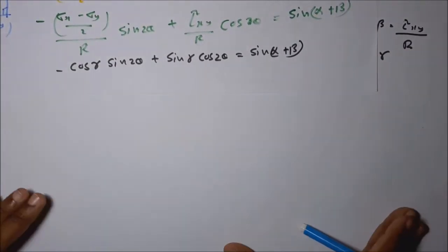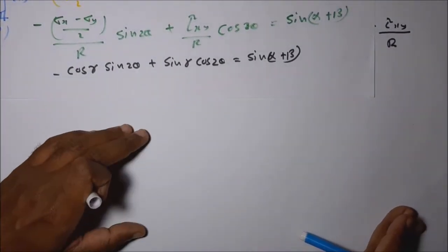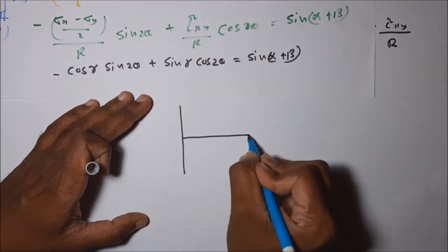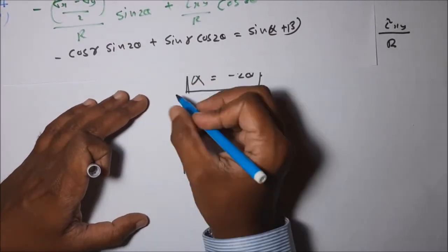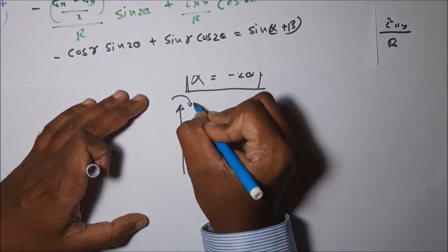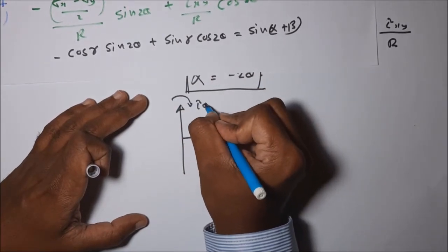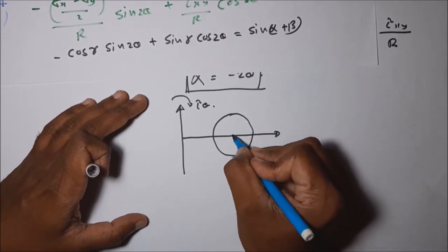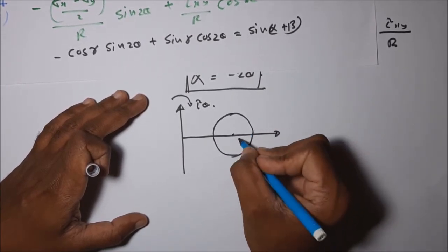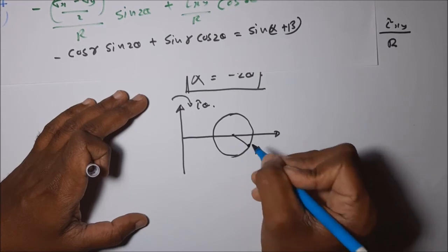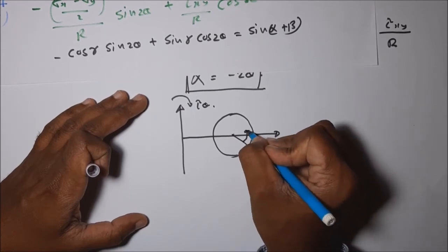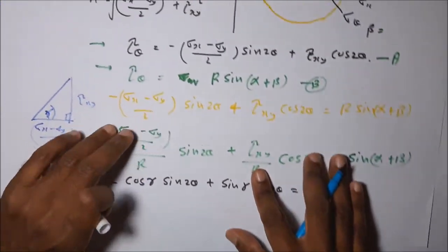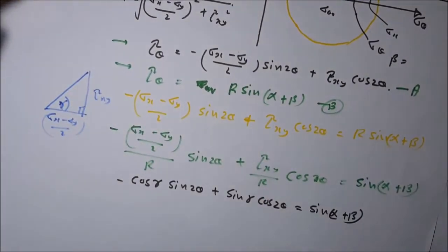That means if we draw this diagram in this way, taking the clockwise shearing stress as positive, then the angle measurement follows the same sign convention we assigned for the two-dimensional stress problem.